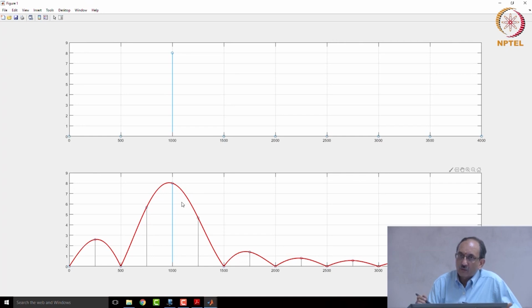So that is like applying a 64 sample rectangular window. The rectangular window has now a larger duration, larger in time, which means in the frequency domain it will be narrower. If it is narrower, the tail interference will be less, and hence when you observe the same sinusoid for a larger duration, more cycles, this sinc will have a narrower width and the peak will be shifted less.